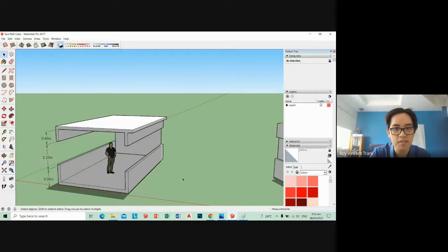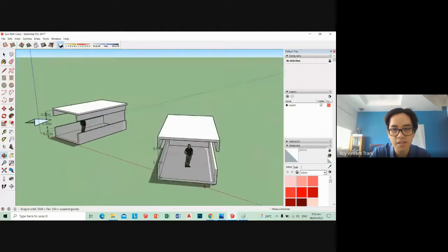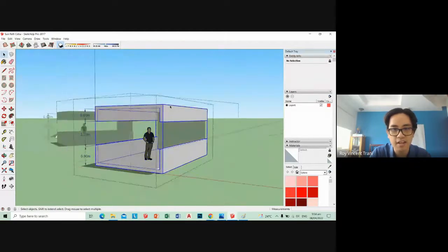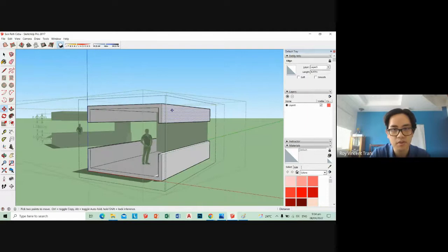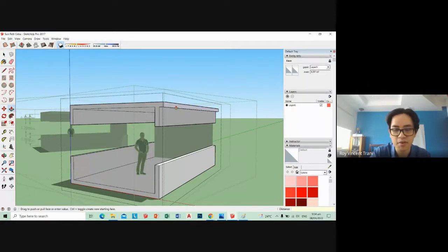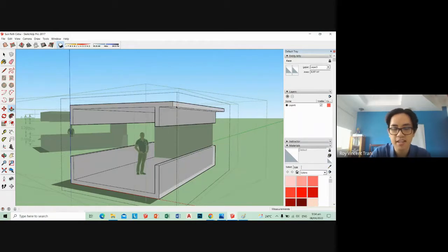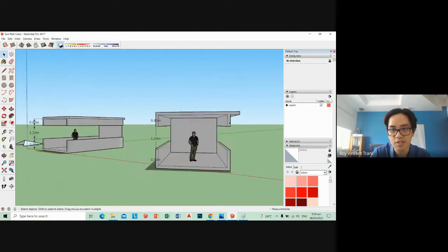See what happens. Oh, no more sun coming in. And then let's say on this end, definitely the sun is gone. 0.45. Oops, sorry, just wanted to check it. So it seems to check out. 0.45 is really all we need. So I was wrong at first, since college, that we need longer eaves. You actually don't need that much eaves.